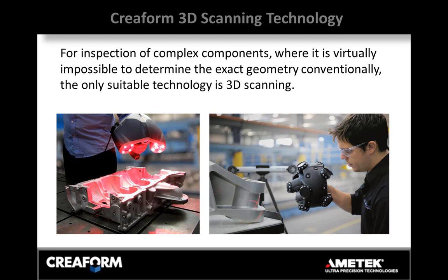Because some parts are not easy to touch probe, for example on a CMM or with an arm-based touch probe, because some parts are slightly deformable, so very unstable, or have curved surfaces, so they don't rest very easy on the place and move around, or in case you need massive data, not only specific points, then the scanning solution from Creaform is very useful, because the scanner is self-referencing itself on the part, and so you always get the data from the part.